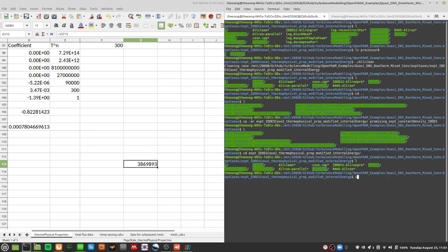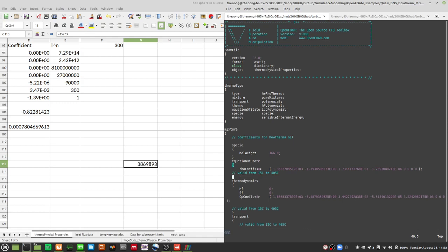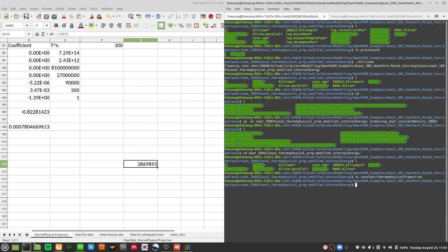Okay, so let me change it back here. You can see that it's promising because we know where the instabilities are coming from. One of these sources is the density fluctuations in buoyantPimpleFoam. Of course, the other possibility for instability is the cyclic boundary conditions being very wonky.